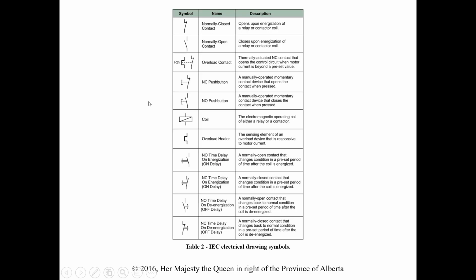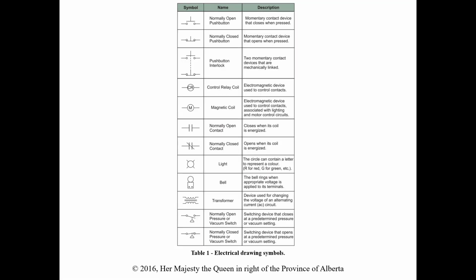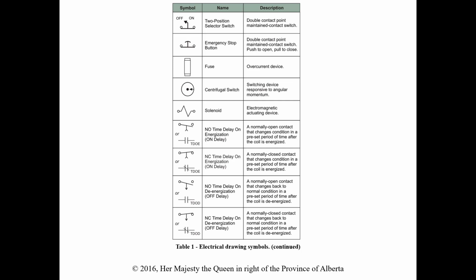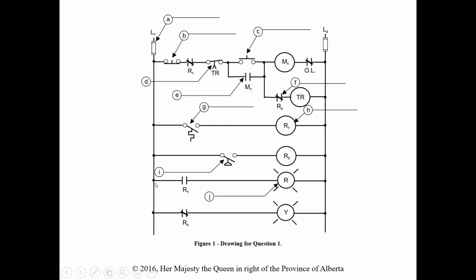Then we have IEC as well. So all these ones we've kind of shown here are more NEMA style. These are the IEC style. So same thing, normally open, normally closed, contacts, overloads, they just look different. And again, you could see either one of these, NEMA or IEC, in your field experience. So definitely know the difference between the two. Okay, so normally I go through and it's a class and we name these things, but definitely go through the mod.